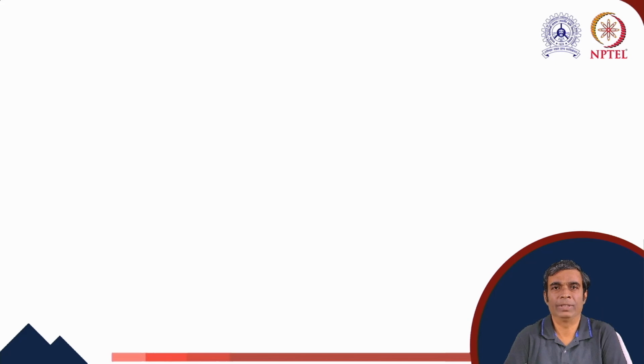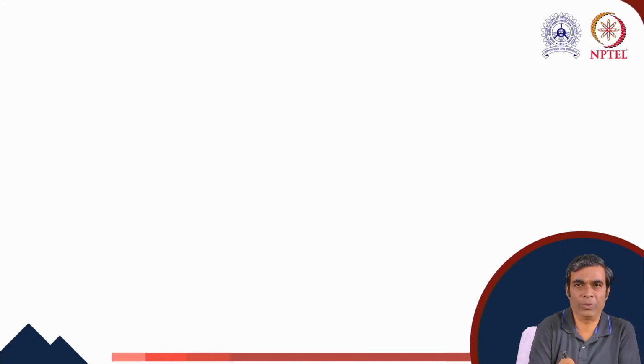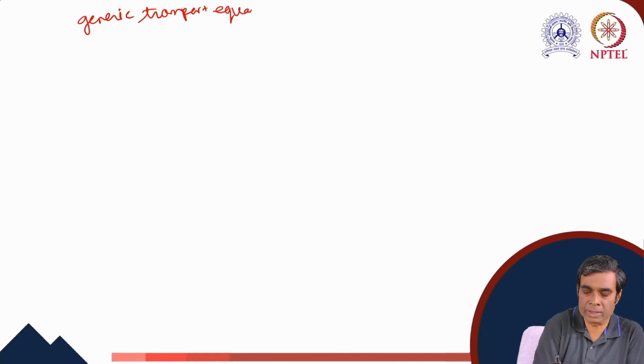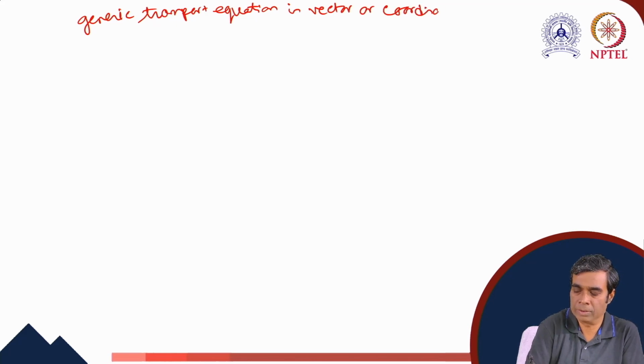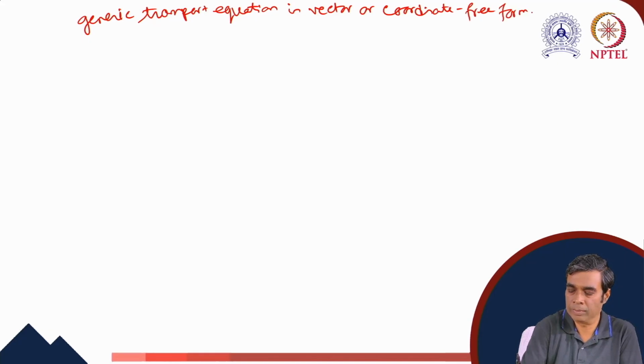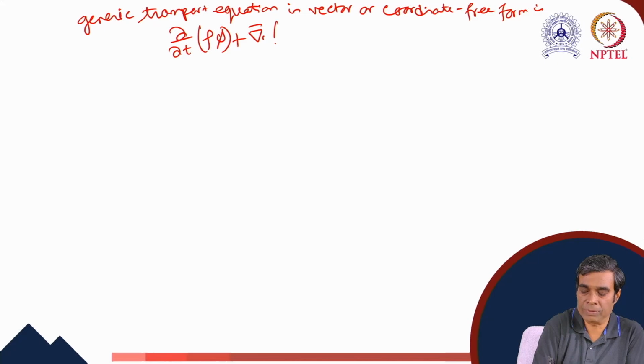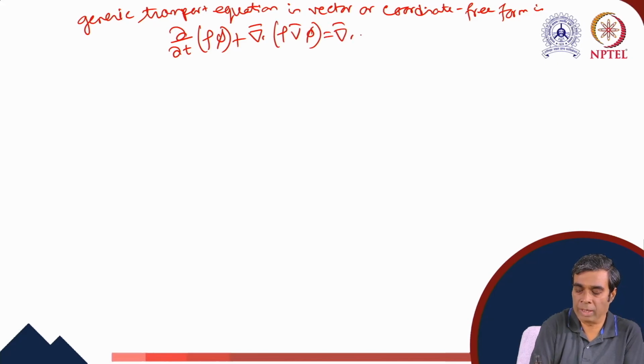Now we have a generalized transport equation. This equation is in vector form. In previous classes I told you that a vector is a coordinate free identity. So the equation which I shall write now will be in vector form or coordinate free form. This generic transport equation in vector or coordinate free form is del t of rho phi plus divergence of rho v bar phi equals divergence of capital gamma grad phi plus s phi.